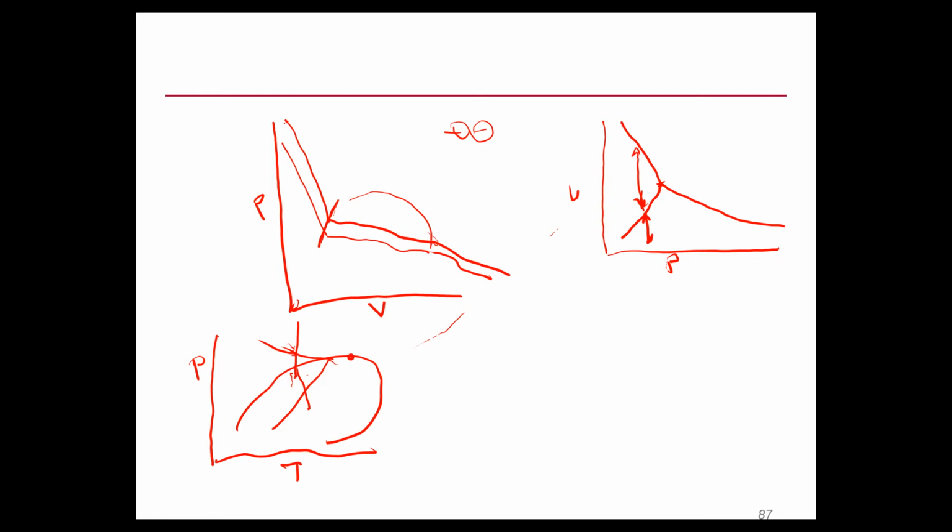The other process that can result in asphaltene formation is acid job, when we inject acid. Why do we inject acid? To improve permeability.